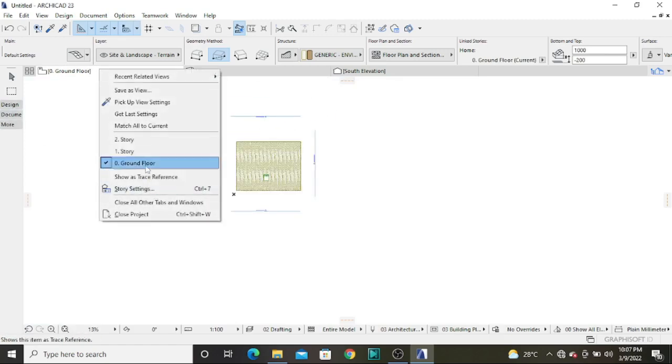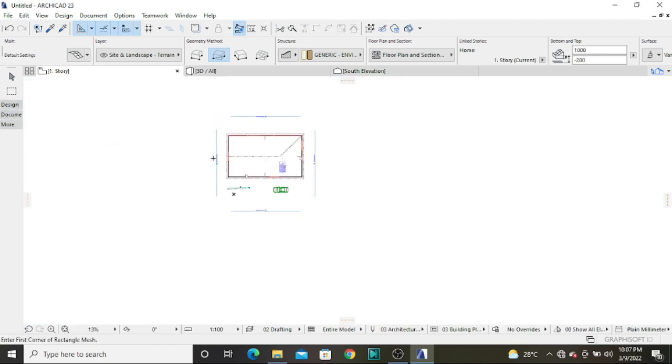Let's go back to first floor, because that is where we started drawing. So in document we also have quite a number of properties. This is a dimension tool used whenever we are doing dimensioning. This is for leveling, whenever we want to know elevations in our structure, including sections of our structure and heights of objects. So it is an elevation tool.